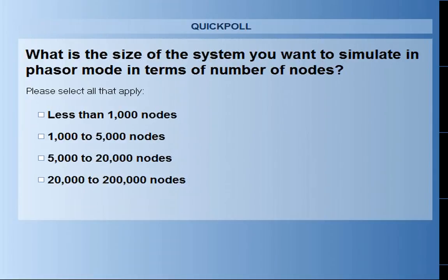The next demo is with the same system, but what we do is that I'm sending the ePHASORSIM data, wrapping it with the C37 protocol, which is provided in RT-LAB, and then the data which is wrapped here can be sent through the ePDC. ePDC is a product from EPG.